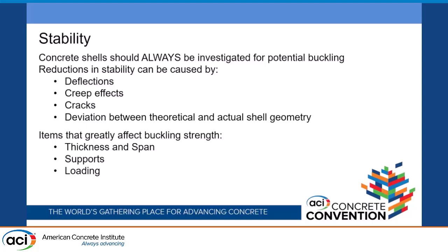Loading is not really as much. Usually shells, especially shells in double curvature, take external loads very well, uniform loads. They can resolve those loads very well. However, at our edges, that's where we get discontinuities in the shell, openings or the terminus of the shell at the foundation or other places.